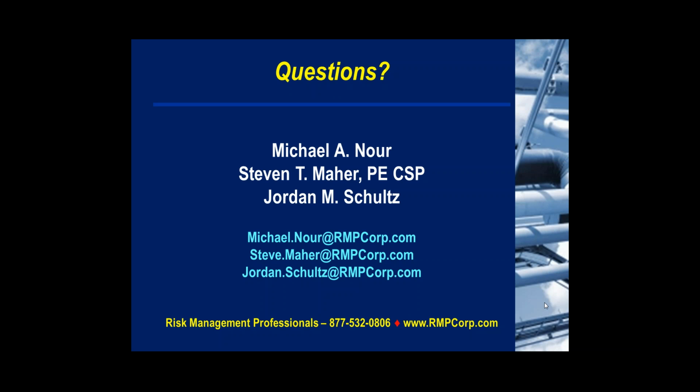For the damage mechanism review, we saw inherent safeguards allow a mechanical integrity or a reliability team afterwards, when referencing the damage mechanism review, to get some added value and to look at the piping metallurgy, for example, as something that could fail, whereas classically in HAZOP, that's something that is not considered as a safeguard that could fail, similar to the non-inherent safeguards.